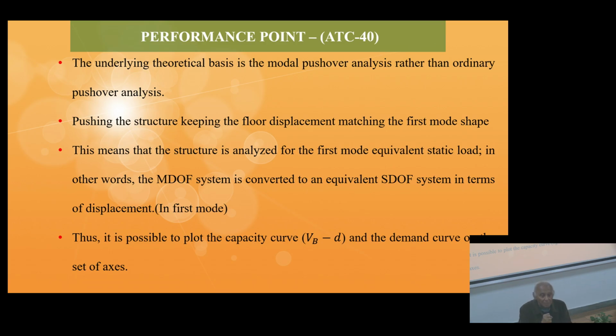So once you have done that, then you have a K, you have an M, you can find out the frequency of the system. Okay. Now, say for example, if you do this for a particular simply supported beam, you will find that the fundamental frequency of the beam, if you calculate by continuum approach, and this way, they differ by 10%.